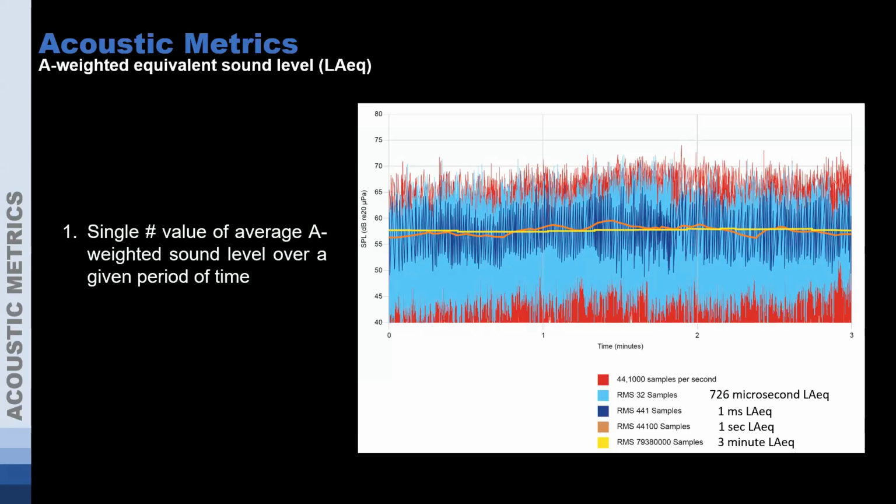But then you actually look through that and see that you're actually reaching sound levels much higher, maybe even 70 dBA during that. But because of that averaging time that you chose or that was chosen, it looks like you're meeting where you may not otherwise actually be. So you've got to watch out for that.